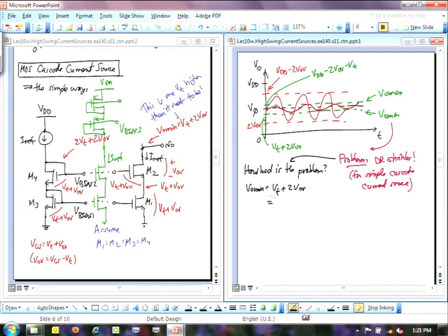What's a typical value for Vt? So that's 0.7, and that's probably what it's going to be for at least this bottom transistor, because the source is tied to the bulk. Right, for this top transistor, it's actually going to be a little larger than that, right? And so I'm sort of taking the best case right here. So that's going to be about 0.7.